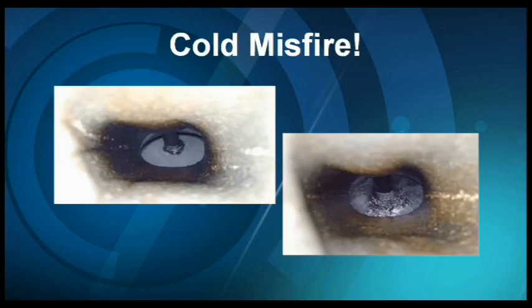As you can see here, we can definitely see the results of the carbon buildup on the back of the intake valves. Now this seems to be a big controversy in our industry on how you would repair this. If the vehicle is under warranty, and this is a little hard to swallow, but at the Ford dealer, they might choose to replace the entire cylinder head.